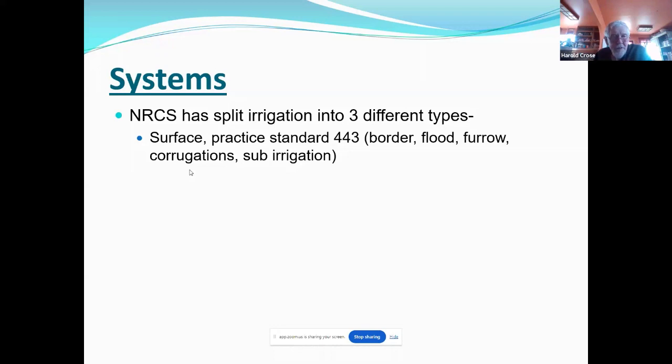We understand that surface irrigation to get to like 40–50% efficiency is a real reach. And that would be primarily based on soil type, length of run, how far you're pushing the water. Those types of things have to be taken into consideration. And water management is extremely difficult on surface irrigation systems. Basically, we do an effective job of irrigating the middle third of the field, where the bottom gets under irrigated and the top gets over irrigated, and they can graph that out quite well.